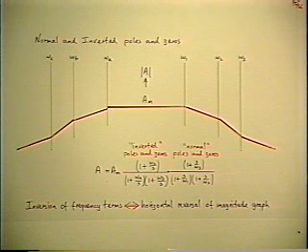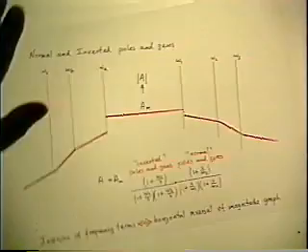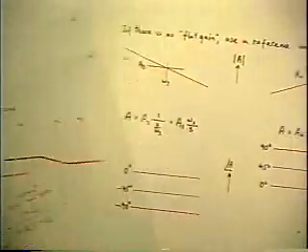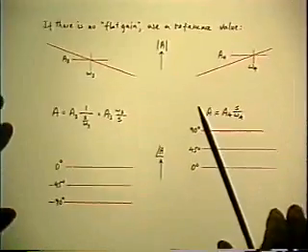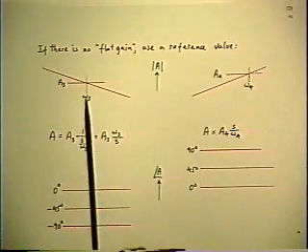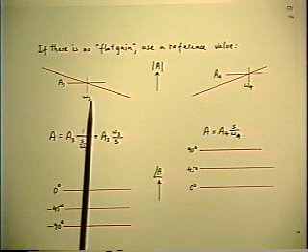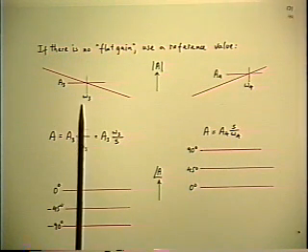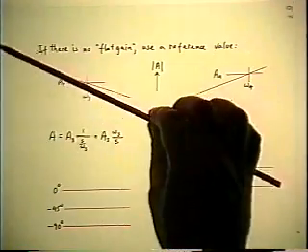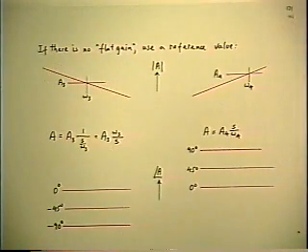Okay. All the examples so far, we've had one flat gain. So let's look at some special cases. Here's a case where there isn't a flat gain. And if we want to write the factored pole zero form, we have to have some means of locating the vertical position of the whole picture.